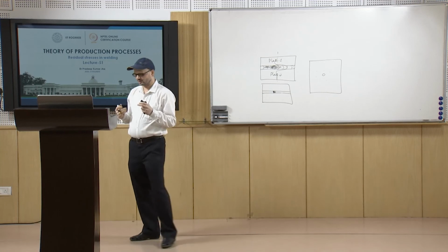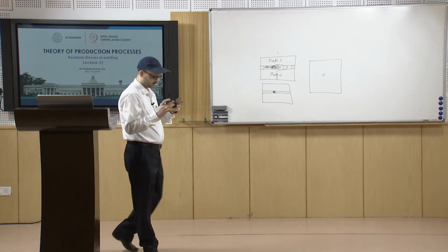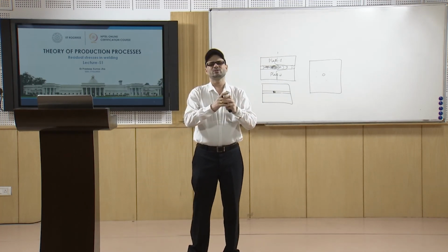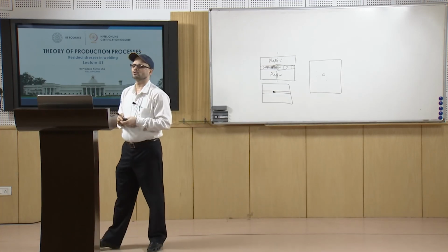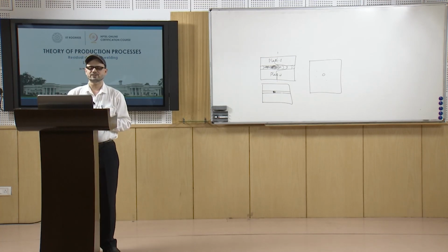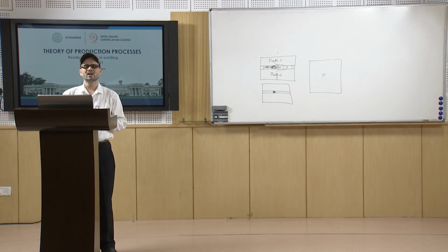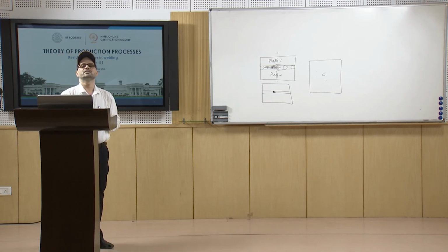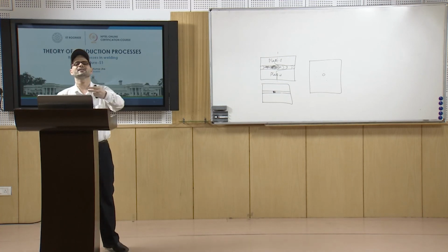Depending upon the position of how these cracks are developing, and you have a calibrated strip there, based on that you can calculate the residual stresses by comparing the results of the stress coat on the job with that of the calibration strip. So, that is done in the case of the brittle coat method.